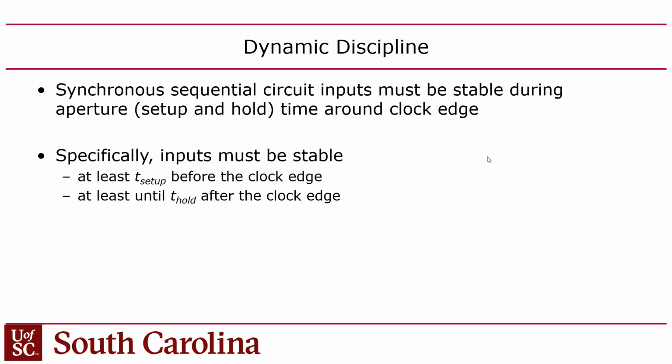The synthesizer may not be able to synthesize the logic to obey the dynamic discipline depending on how much behavior you have inside of one clock cycle, right? Okay, so the dynamic discipline means basically that the logic should be synthesized such that you don't violate the setup and hold time for any flip-flops in your design. Okay?